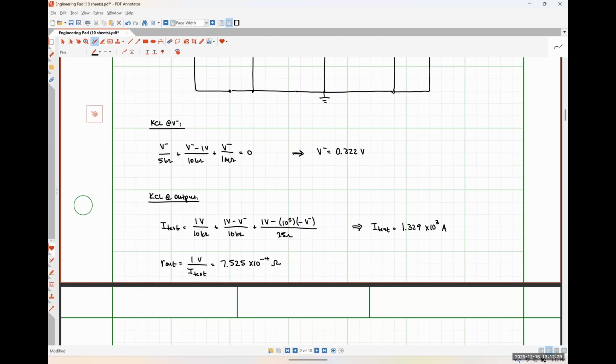All right, so thus far, we've talked about calculating open loop gain, or excuse me, closed loop gain, which we successfully did by just analyzing our circuit using the practical op-amp model. We've also made a few observations. So our differential voltage was incredibly small. The current that was flowing into our input impedance was incredibly small.